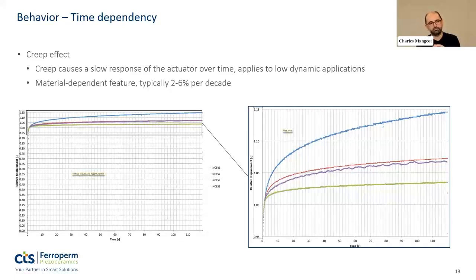It happens quite fast. It's not a fatigue; the material doesn't have that much fatigue. So if it cracks, that's it. On a typical actuator like NAC 2013, for example, we test around 9 to 12 kilovolts per millimeter. That means 3 to 4 times the nominal voltage can be applied before the actuator just breaks itself.